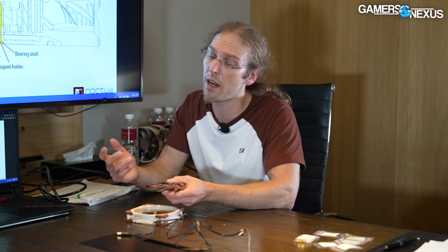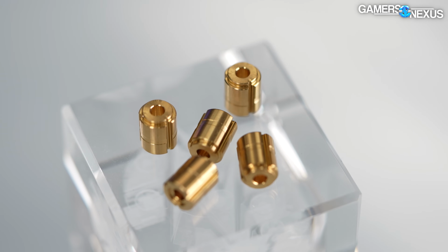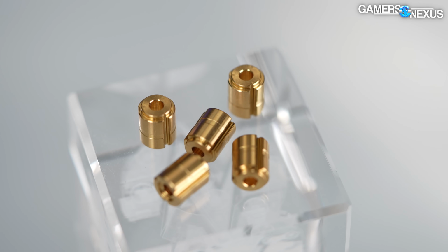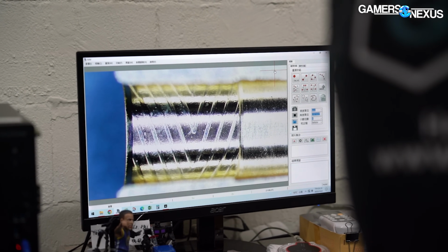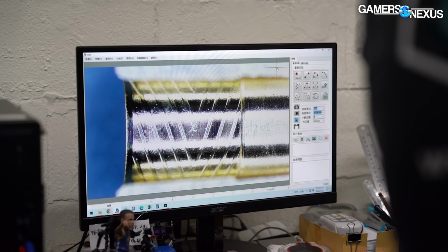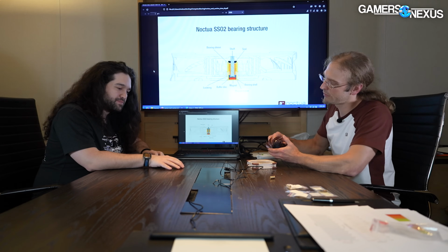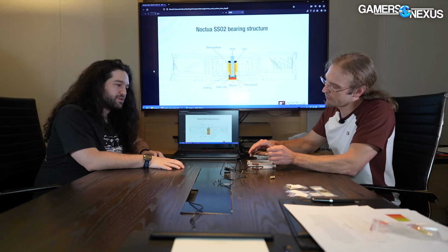You can also run into acoustic concerns with the lubricants, and all the groovings have the downside of adding additional complexity that needs to be controlled from a tolerance perspective. So if you happen to have those nice grooves and rough edges on them, this is something that will be audible.